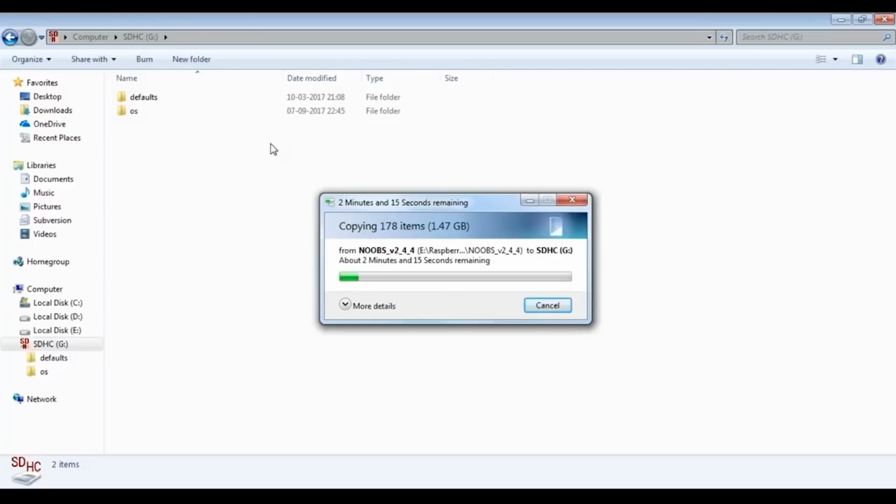Now again, this is why I recommend that you use a high-speed memory card, because in case you're not using it, it takes a lot of time with respect to fetching the data. As I had mentioned, if you're going for a memory card for your Raspberry Pi, you can use something like a 16 GB at least and make sure it has a high transfer speed. This in turn will give you a lot of memory area to work around with, and I would recommend you take something like a class 10 memory card that is available in the market today. These have a very good read and write speed ratio. So definitely this is something that you should consider while you're getting a memory card for your operating system.